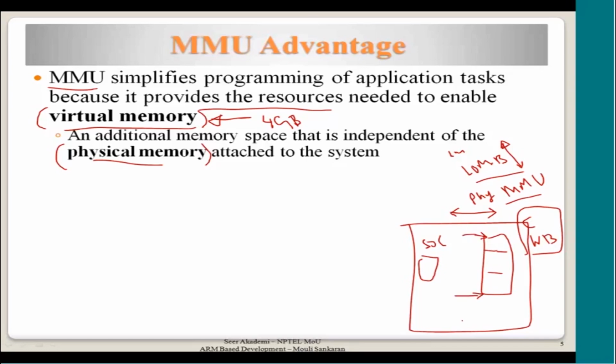The board should also be accordingly designed, or you have to modify your memory map of the physical memory based on the board design, which address it is referring to, so that you know where the physical memory is residing, so that you can configure the MMU which is sitting in between, so that you effectively run your code on the board.